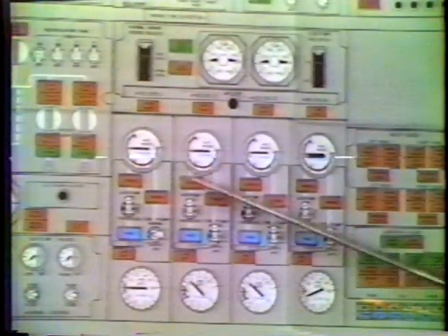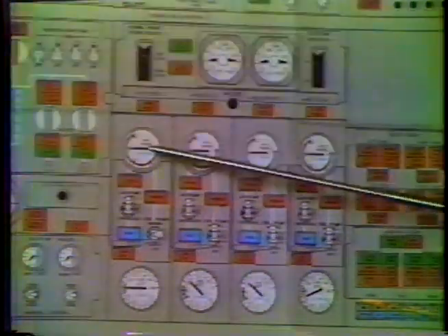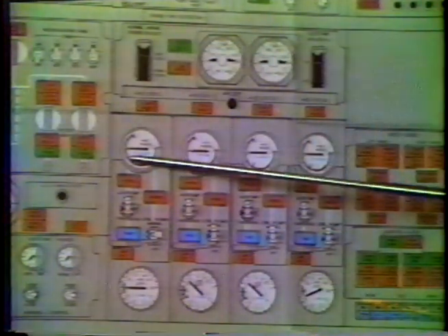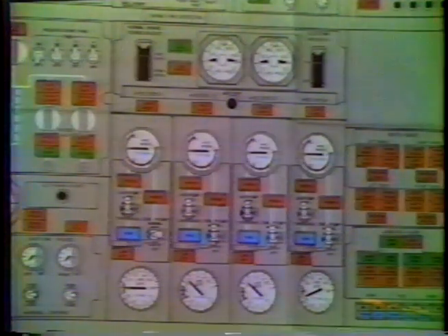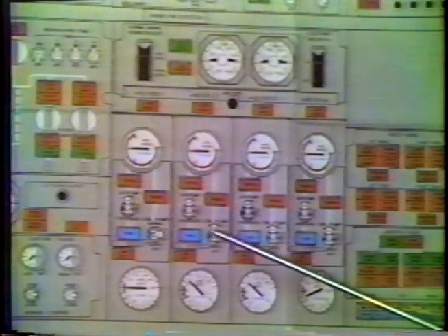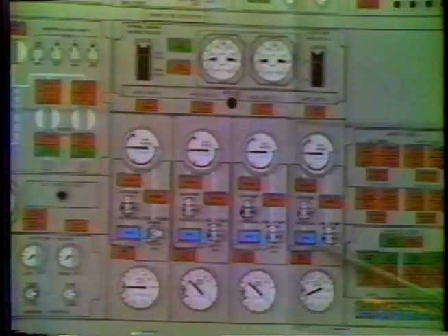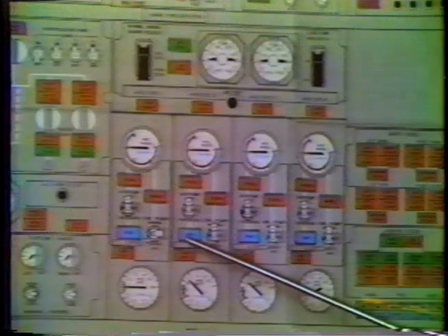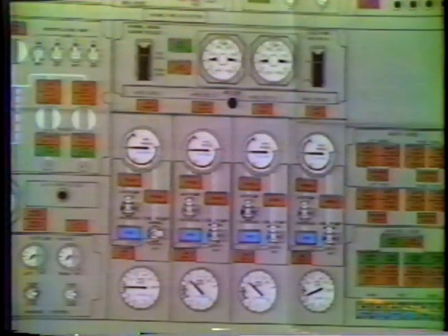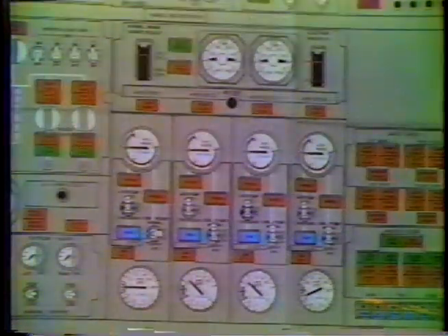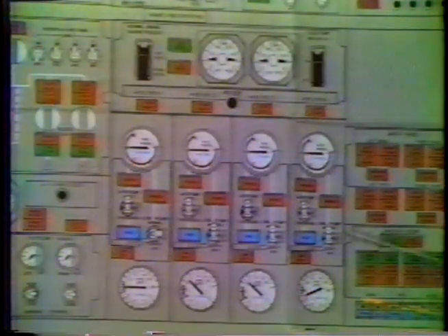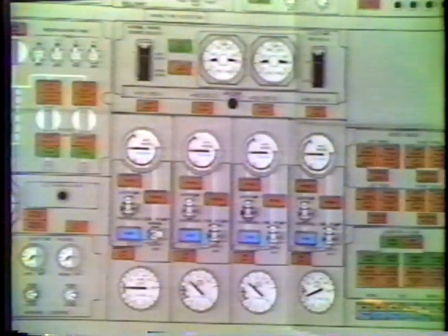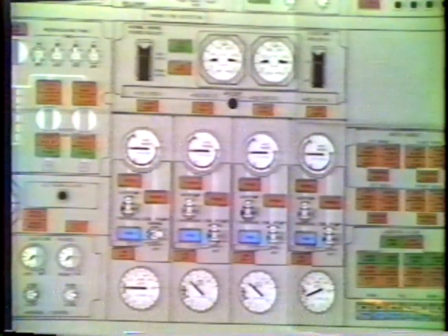Generally, in the auto position, it will activate the pump when the pressure drops to a value where it requires aid to bring the pressure back up to normal. And in cruise, normally the engine pumps supply all the hydraulic pressure. However, when activating a major item, for example, the gear, flaps, or speed brakes, it would cause the air pump to come in and help. In the auto position, once the pressure is back to normal for approximately 10 seconds, the air pump will automatically shut itself off.